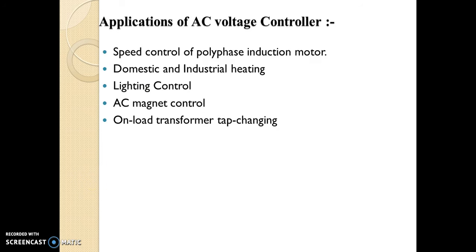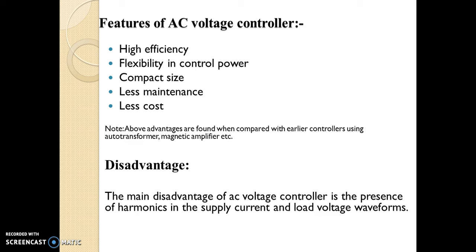The applications of AC voltage controller. There are many applications of AC voltage controller, but I have mentioned some of them. The first is speed control of polyphase induction motors, domestic and industrial heating, lighting control, AC magnet control and on-load transformer tap changing.